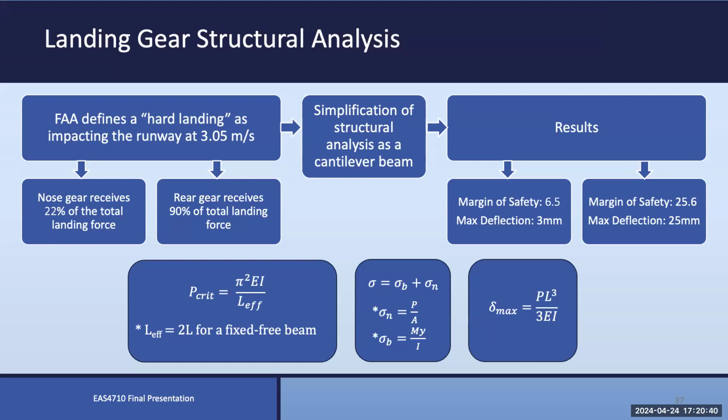So what you'll find if you wind up doing composite analysis professionally is that your modulus is going to depend very much on the angle that you lay your fibers up at. A 90-degree fiber is going to be very weak in compression, and a 0-degree fiber is going to be very stiff in compression.